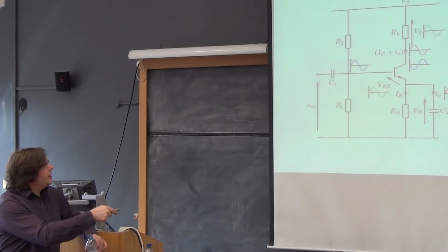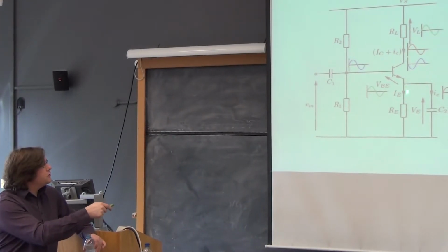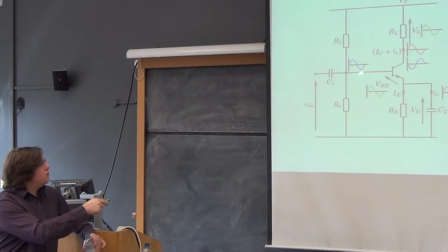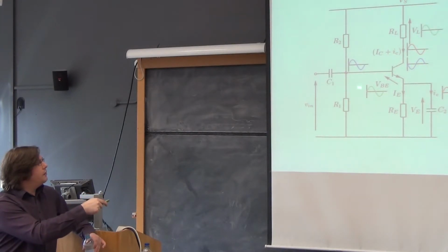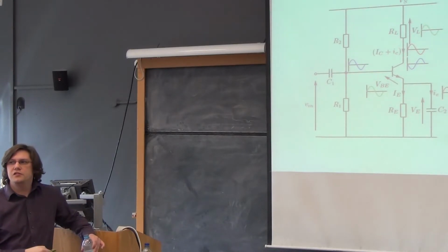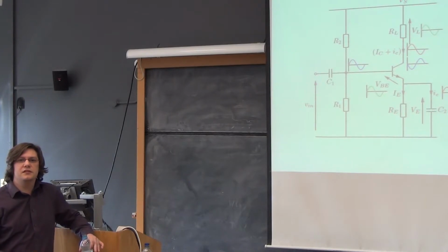So that means that having reduced the signal voltage across the RE C2 parallel combination, we've now got almost all of VB, the voltage across R1, which is the voltage at the base, appearing as VBE. So the transistor's gain appears not to be reduced anymore. The transistor's gain doesn't actually change.